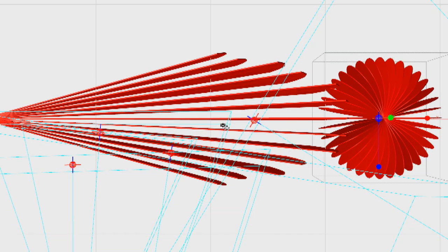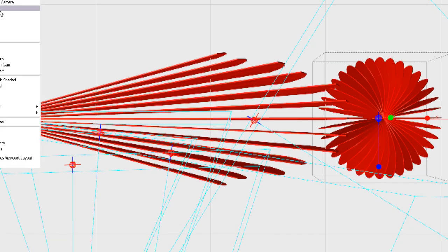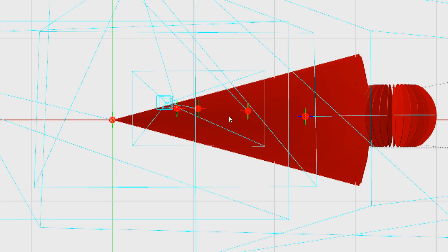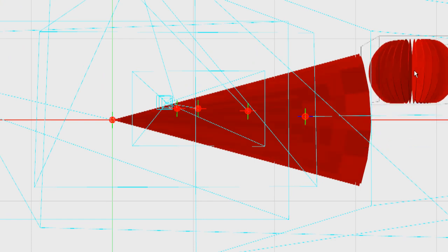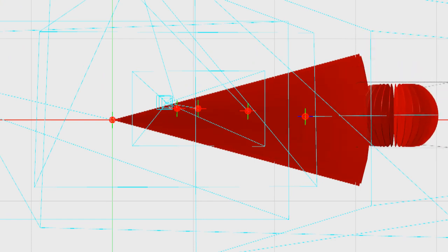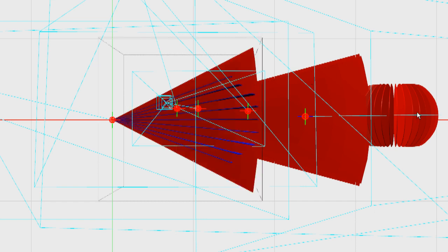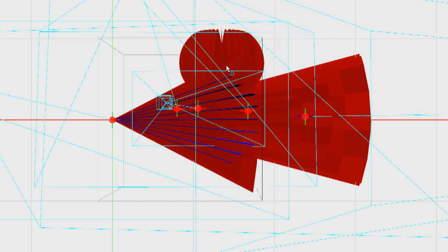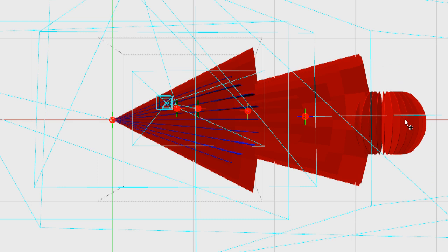And not only that, the range is significantly higher. So again, here's your Yagi range. We're all the way out here, look. And let's compare that to the diversity antenna, which is pretty good range. Let's get the pattern on for that. Is here, yeah. So we can get to about here with your diversity, 11 decibel. We can get all the way out to here with your 15 dB Yagi.